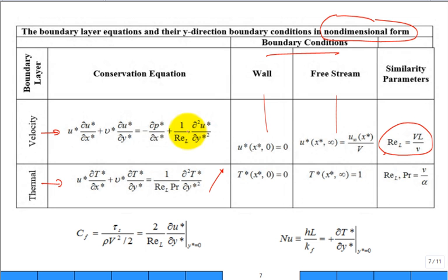That's why the Reynolds number characterizes a lot about the shear stress at the wall, and it shows a lot about when it's laminar or turbulent. It shows up right there in our equation in dimensionless form. When you do it for the energy, a parameter shows up which is a Reynolds times a Prandtl, the same Reynolds number times the Prandtl number, nu over alpha.